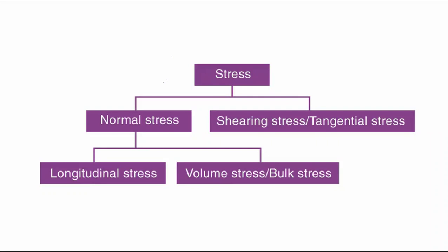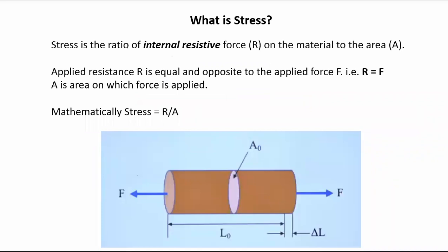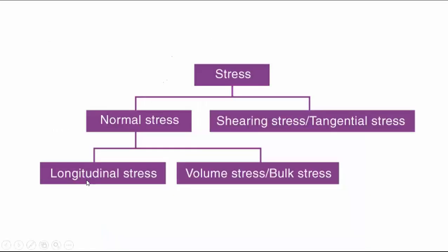Here you can see the different types of stresses, all the types of stresses which will be useful for finding SFD and BMD, which we are going to discuss in today's lecture. First is the normal stress. In the previous slide, you have seen that if the force is applied normal to the particular surface, the stresses generated in the longitudinal direction or the transverse direction will be called normal stresses. Here you can see two types, longitudinal stress and transverse stress.